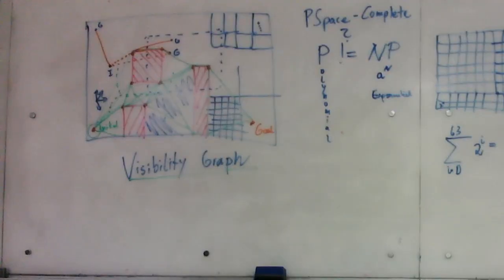So in that case, your path planner, last time I talked about correctness of an algorithm and completeness, right? If you inflate the obstacles, the algorithm will still be correct. If you generate a path, that should be the path that will get you to the goal. But it may not be complete anymore, because now you will have ruled out some possibilities of solution.